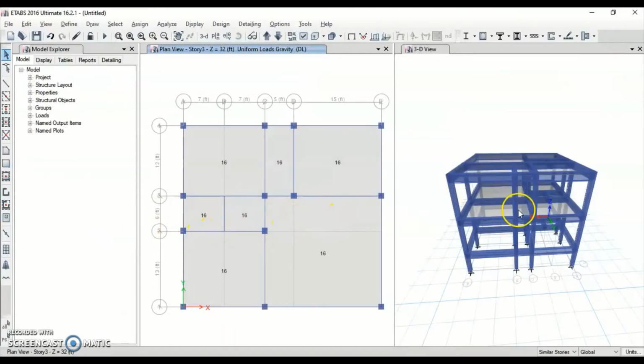So now in this case, I need to only apply this load to this floor. We don't need to apply it unless this is considered to have a dwelling or residence there. But in our case, let's assume that there is no load here besides the minimum roof load that needs to be provided. So we need to apply this live load only to this particular floor.